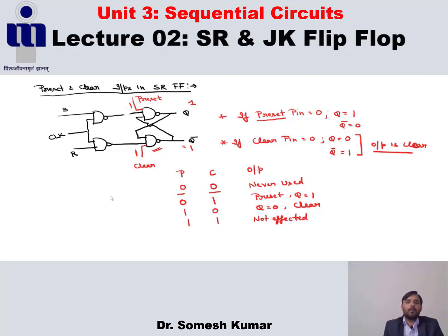So if preset is 0, then only this pin becomes active. And if clear is 0, only in that case it becomes active. That's why preset and clear in SR flip-flops are active low pins. Why active low pins? Because these pins become active when the value 0 is assigned to these pins. Only in that case does this become active.